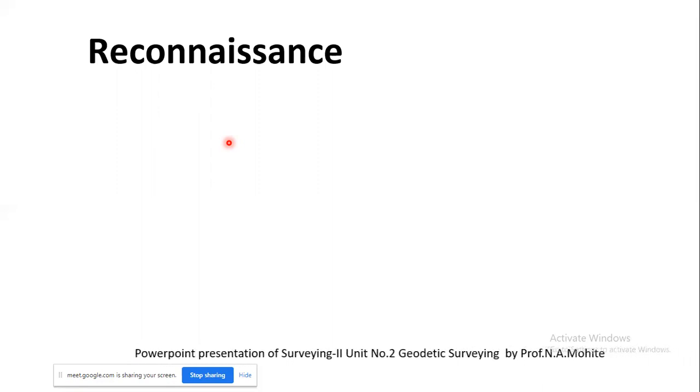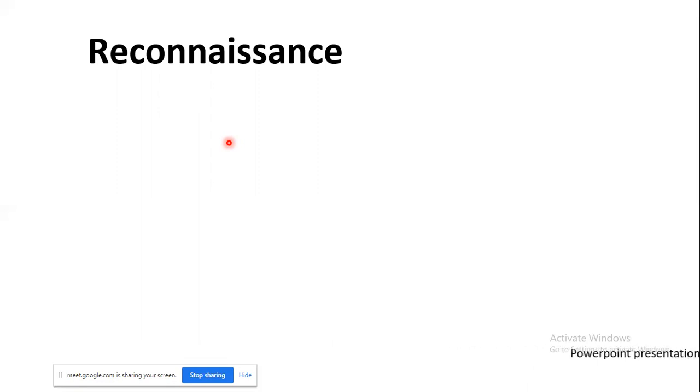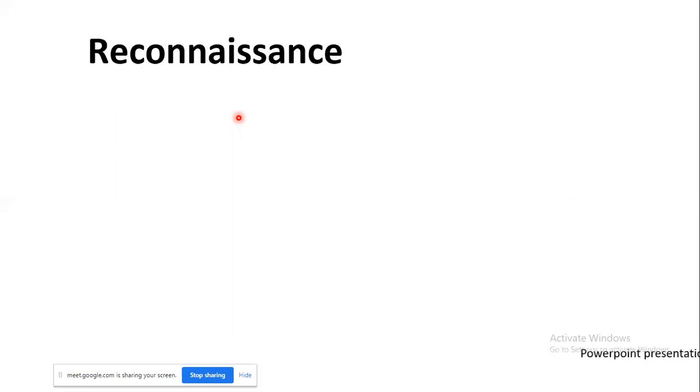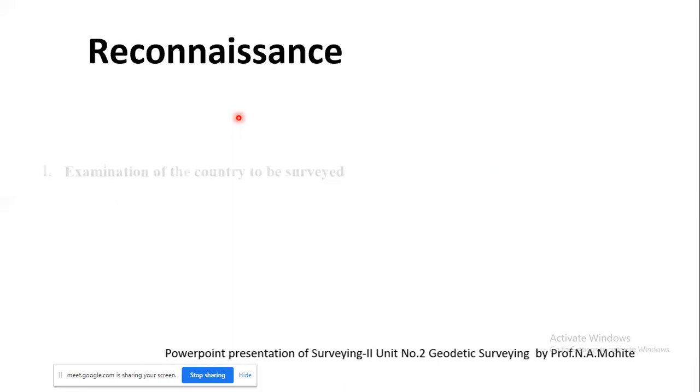As I told you, you are not going to carry modern equipment directly. You are not going to make use of the total station or DGPS, which are costlier. You can take a pocket tape and correspondingly small equipment, minor instruments. In order to measure the slope, you can go with the prismatic compass. You can also have small binoculars, so that if the area is a larger one, you can see through them. That is nothing but your reconnaissance survey.